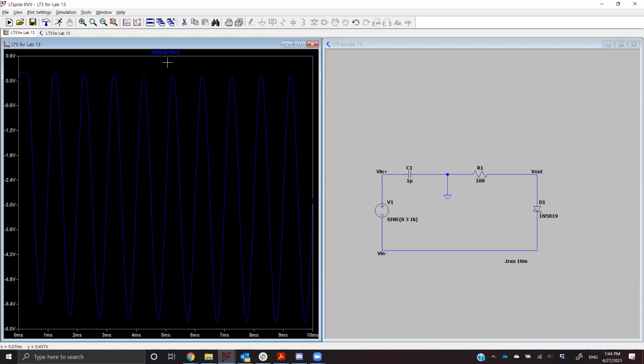Well, first of all, why would we want to do that? In this lab, for the rectifier and the regulator circuit, you'll see that the output voltage will have some initial transient for the capacitor to charge up. But that's really not what we're interested in. What we're interested in is what happens after everything settles down, and what we as humans or experimenters will actually see the circuit doing, right? So the initial transient happens, but it's not what we're really interested in.